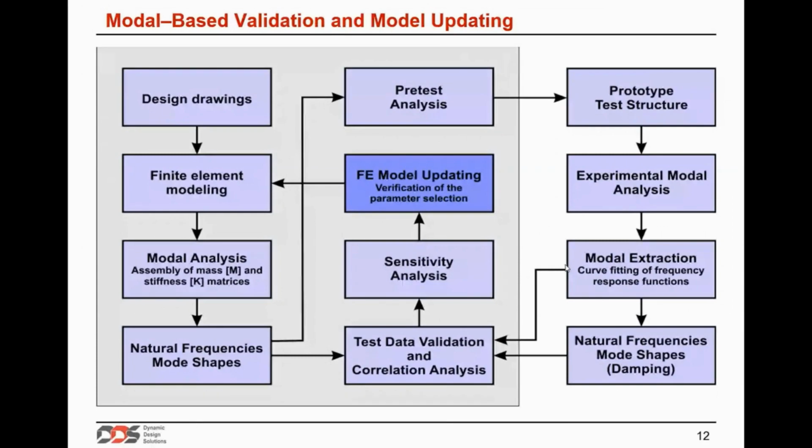Modal-based is the most popular approach because the test data is relatively easy and fast to obtain using modern technology like accelerometers, using operational modal analysis. So it is relatively easy to obtain good quality reference data like frequencies and mode shapes, which can be compared to the result of simulation, in a correlation analysis, in sensitivity analysis, and in updating.